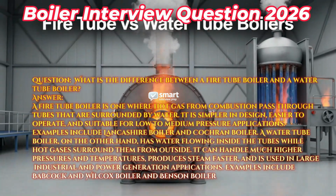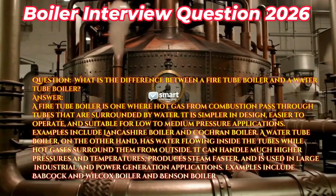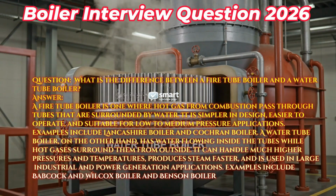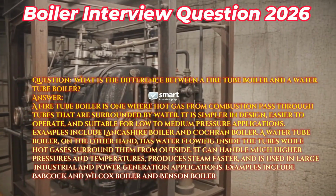Question: what is the difference between a fire tube boiler and a water tube boiler? Answer: a fire tube boiler is one where hot gas from combustion passes through tubes that are surrounded by water. It is simpler in design, easier to operate, and suitable for low to medium pressure applications. Examples include Lancashire boiler and Cochrane boiler.